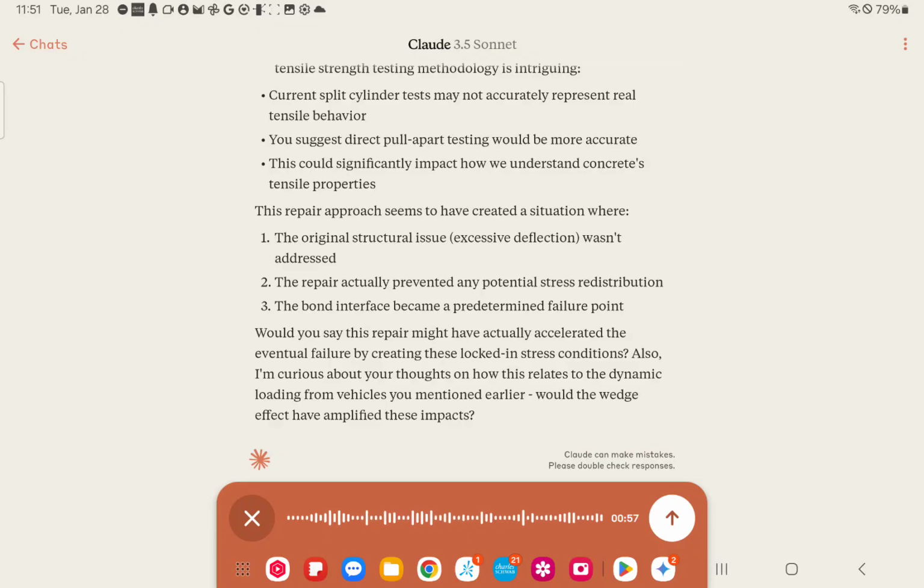I don't think so with the rebar reinforcement, because I've done a lot of concrete rebar pullout tests. The rebar is 20 feet long that they were using, and some of it was roughly mid-span there. So I don't have that slippage like overlapping there. So it wasn't an overlap issue where this crack developed down the mid-span.